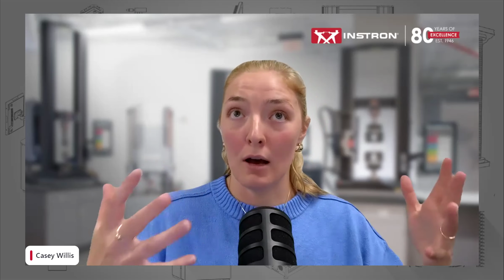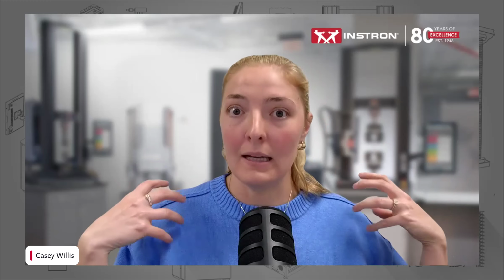If we're assuming you have an AVE2 that has fixed lighting, some of my recommendations for you would be to maybe slightly adjust your light bar away from the specimen. Maybe that fixed illumination is too bright. Secondly, if your specimen's behaving like a mirror, you could paint the specimen and then apply marks. So then there's not this wealth of light getting reflected back at the device.